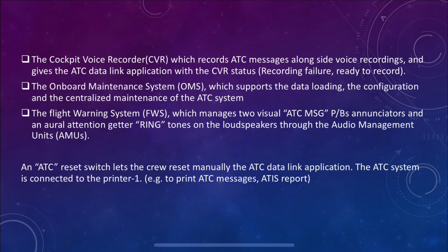The Cockpit Voice Recorder CVR records ATC messages alongside voice recording and gives the ATC data link application the CVR status, such as recording failure or ready to record. The Onboard Maintenance System OMS supports the data loading, the configuration, and the centralized maintenance of the ATC system.